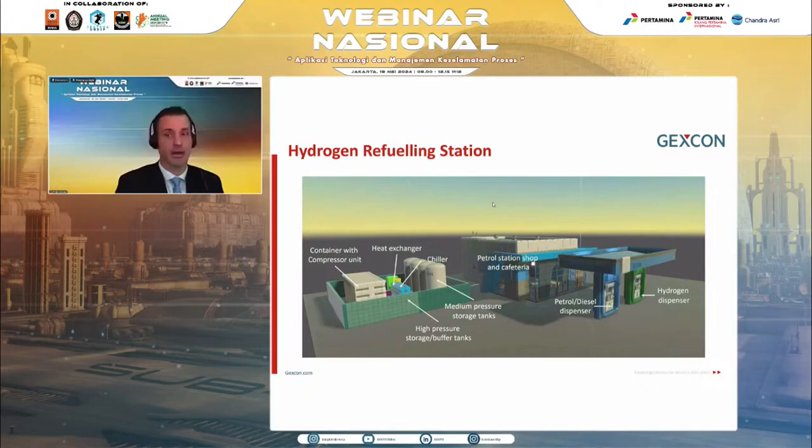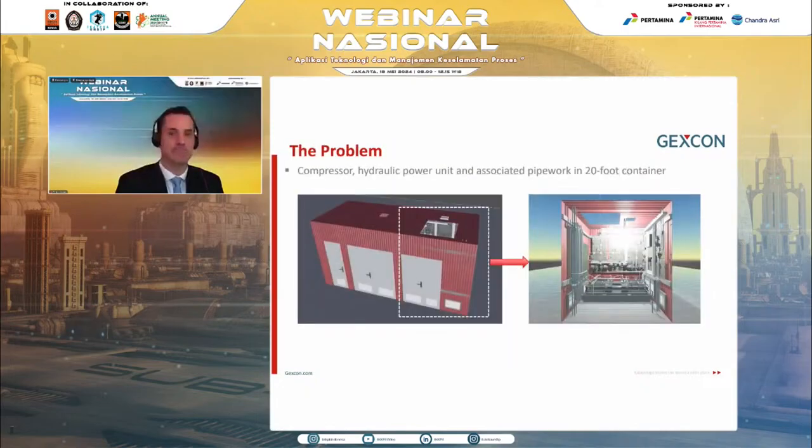What do we want to know that CFD modeling can tell us? Is the ventilation provided sufficient to dilute the hydrogen leak below the flammable limits? If there was an explosion, what overpressure can be expected? Can the consequences of an explosion be mitigated using explosion relief panels? So let's find out and start with defining the worst case credible scenario.